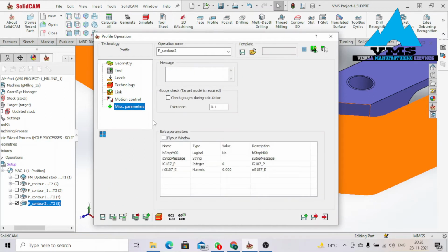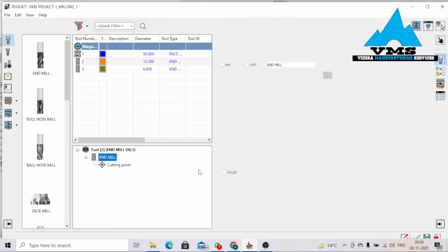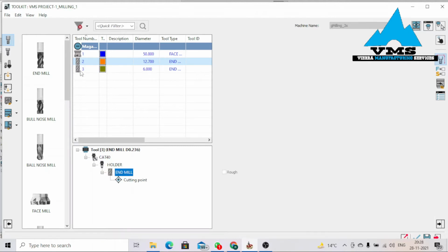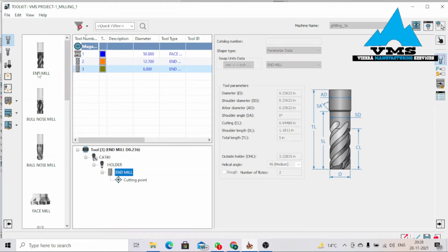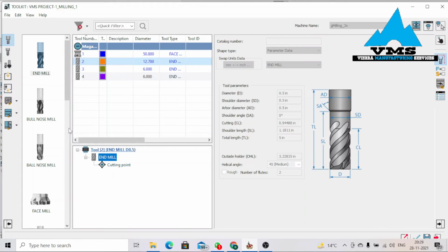Okay, all looks good, guys. One thing, just come back on tool, select. Anytime this kind of scenario happens, it means the tool is actually small, right? So just come on that tool, click and mill. You notice that the holder comes back, so it means this is just a software issue.